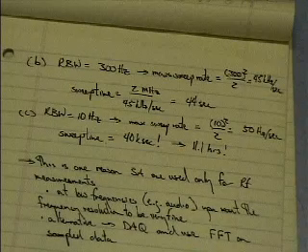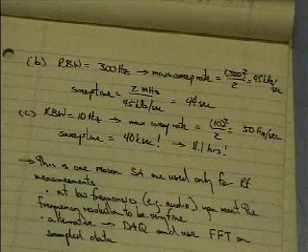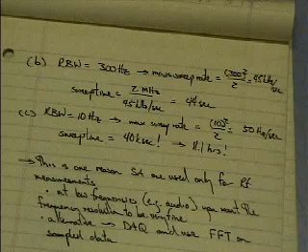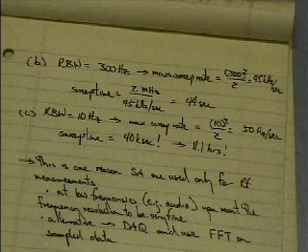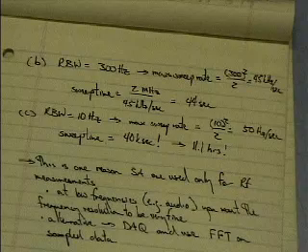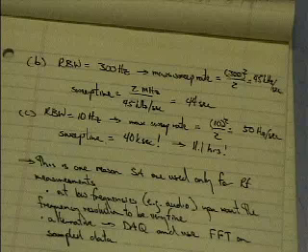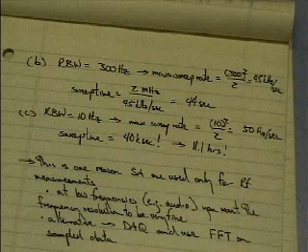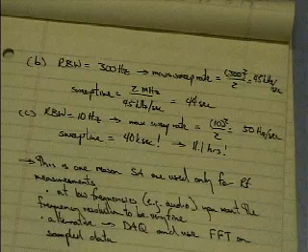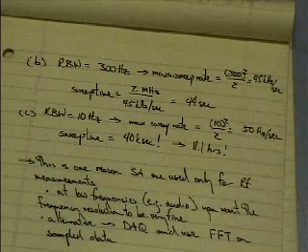Now we say, well, 10 kilohertz, that's a pretty big distance. Well, it is when we're talking about audio signals. But when we're talking about radio frequency or RF signals, we're talking about signals that are spaced megahertz apart. So a res bandwidth of 10 kilohertz is very, very fine relative to the RF frequencies. A thing to keep in mind is the type of signals that we're looking at versus the type of signals that we may have looked at in 171, audio signals. We're not looking at audio signals anymore. We're looking at radio signals.